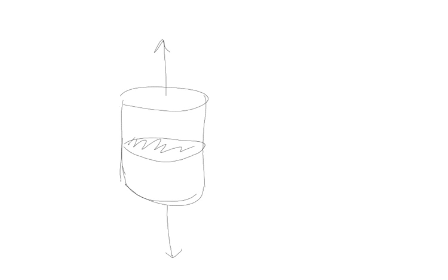Well, people have done experiments on this, and what they find is that obviously it all depends on how you apply this force at the end. If I apply a point force, I just apply this force at a single point and I pull, then obviously right on the surface where I'm applying that force, it is only applied here. But people have found that very quickly, as you go further and further away from that surface where the force is applied, that force starts to spread itself out.